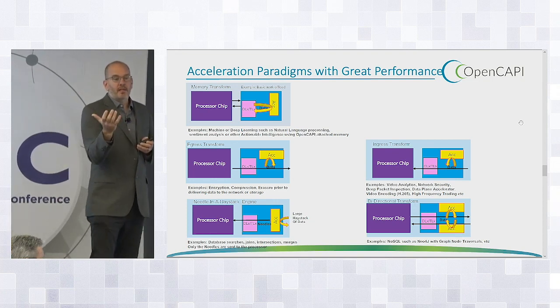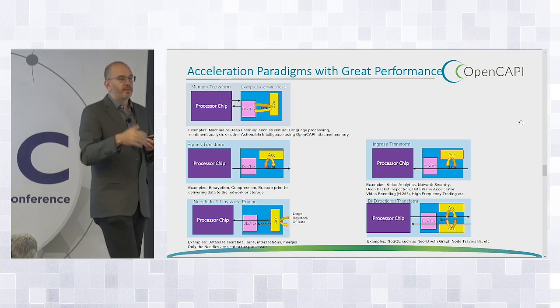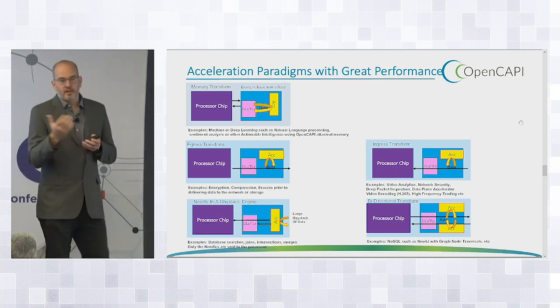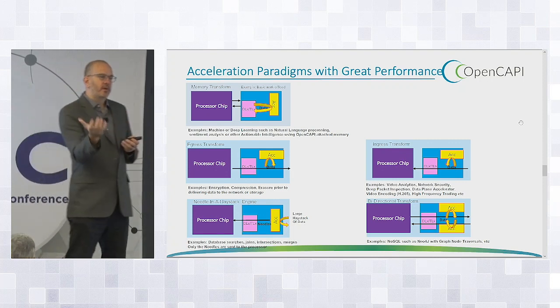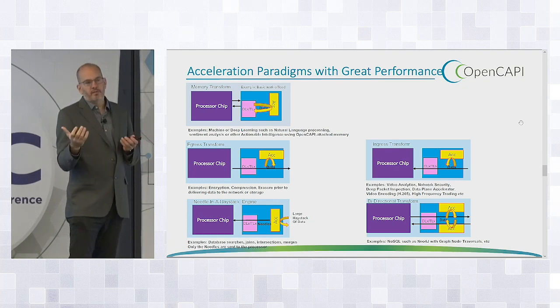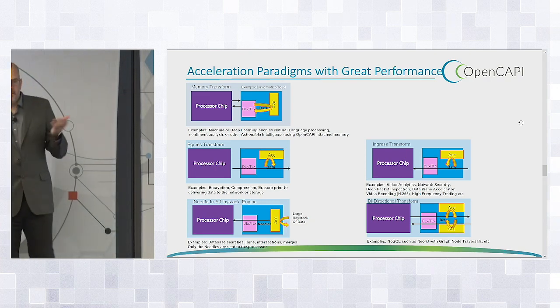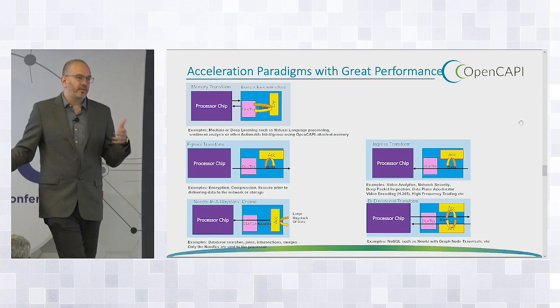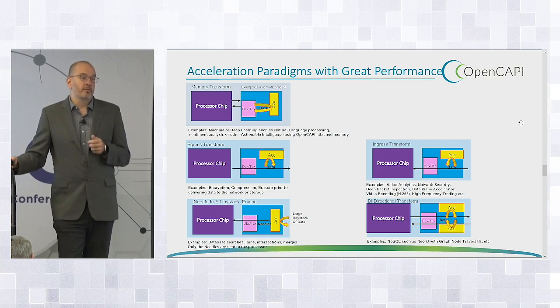But to do so, maybe it needs to talk to the processor to learn encryption keys, or figure out what decompression dictionary needs to be used. So you get this hybrid approach where you have a memory device that looks like loads and stores, but it's a smart memory device. It needs to be able to initiate accelerated operations and master commands. That's another thing you don't get with the DDR interface: the accelerator can't generate an interrupt, it can't issue a load, and it can't be its own master.